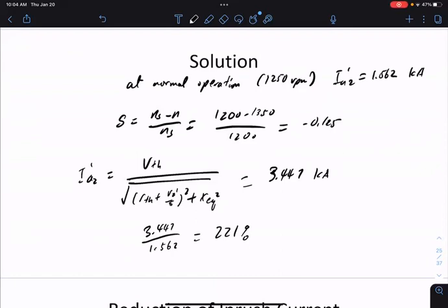Your protection devices do not like this kind of dynamic range for your current. At some point this will start to look like a short circuit fault, but then it's just a normal connection to the grid. Large current again damages equipment and trips protection. So there are a lot of challenges. We have a very large inrush current.